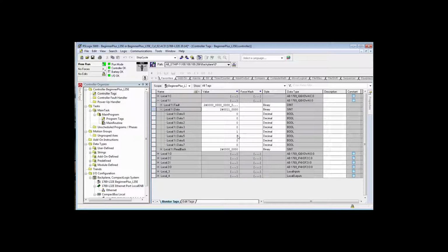And I'll go over to my switches and turn them off. These are real inputs. If I try to turn this input on, put a 1 in there, it's not going to take it, simply because I put it in there. It may have actually gotten into memory, and it may have actually changed that memory location for about 100 or so microseconds. But because you're updating the state of those bits from the real input modules 5-6 times every thousandth of a second, you might as well say it just didn't change.